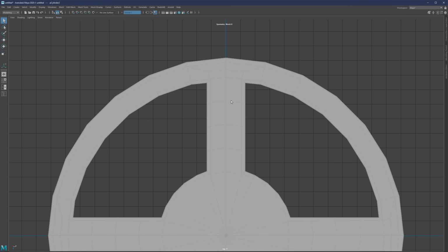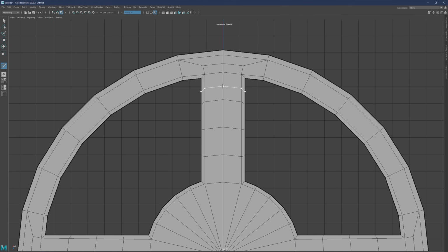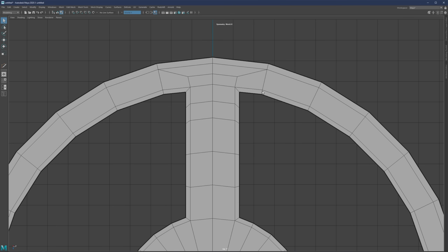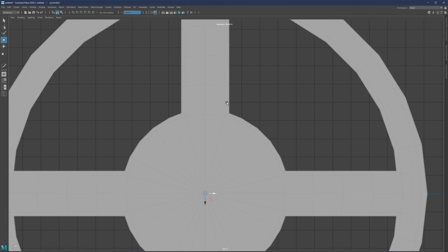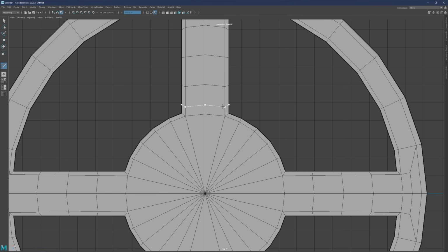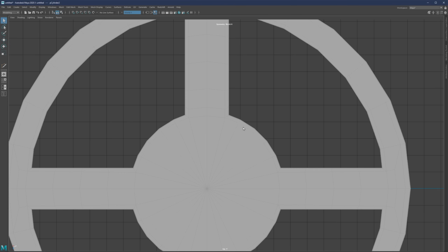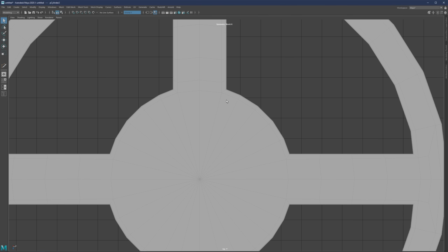Second thing is you can try and redirect some of the edges where maybe redirection is possible, because now we cannot just slide this point, this edge to this one, because again we're going to destroy the integrity of the circle. So in that case, yeah, we're probably going to need to redirect some of the edges, and then we're gonna get something like this where the edge is going to look a bit tighter, but this area might be a bit tricky. Simply because we can add one edge here, which can sharpen it up, but there's not much really that we can do with this one.